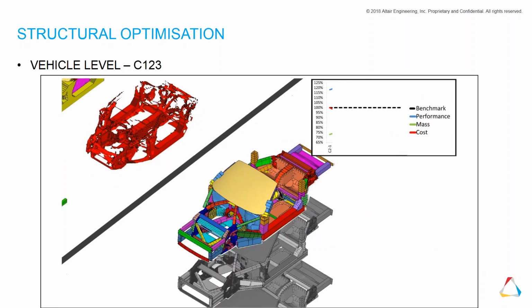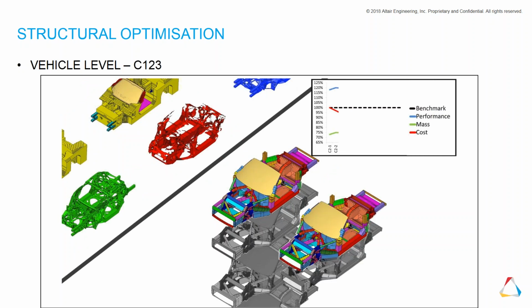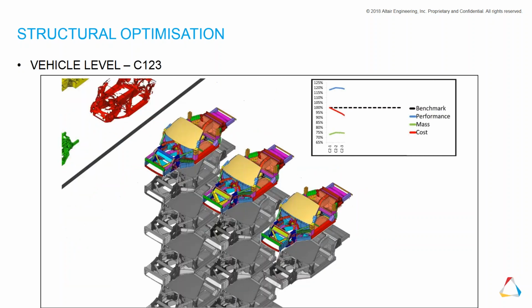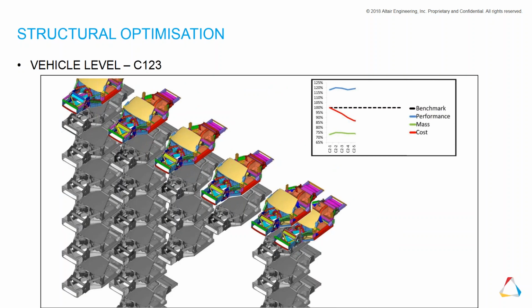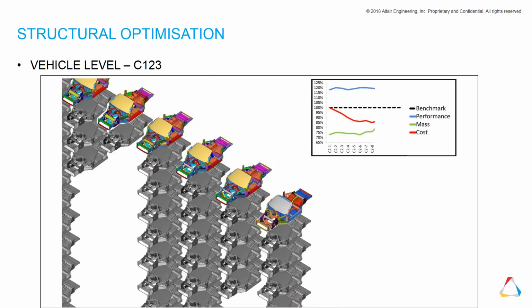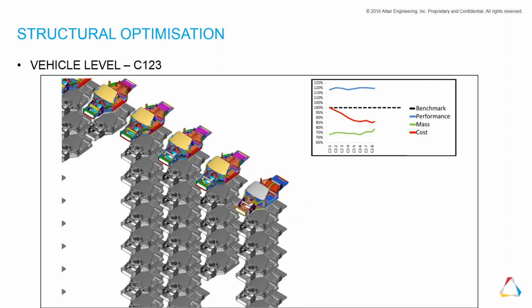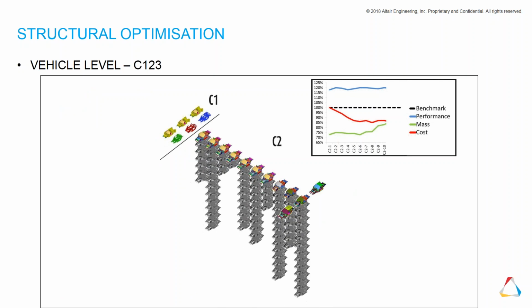We then take this into C2 phase, where we do a quick interpretation in 2D and 1D beams and shells, which, as I said, can then be run hundreds and thousands of times to come up with a final solution, which then moves slowly as you get more confidence into what's called a C3 model, where we'll have full fidelity shells, solids, and 1D rigids.